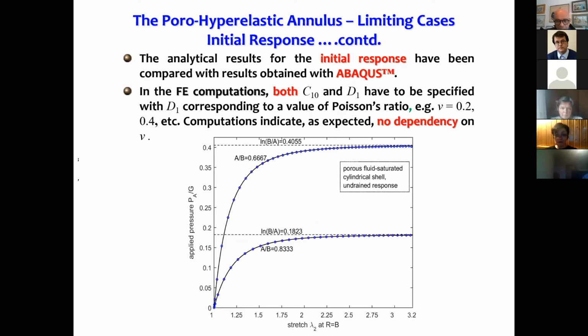instabilities occurring. In other words, you can get stretching for the same pressure. So that means there's a balloon, right? When you blow a balloon, it takes a little pressure to get it started, but once you get a certain pressure, it'll start growing. So this is like a ballooning effect, and people are concerned about this because in blood vessels, for example, you can get aneurysms developing.